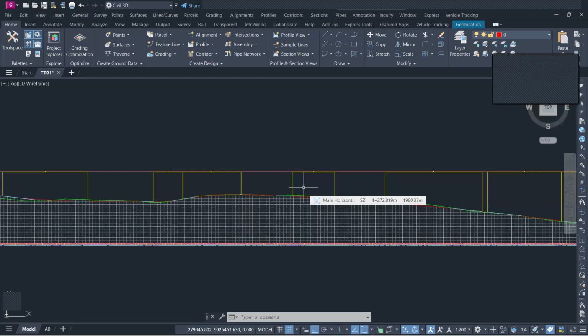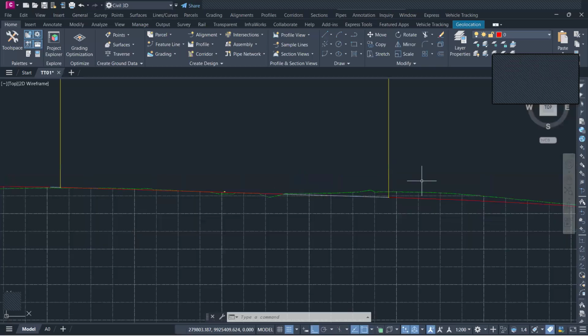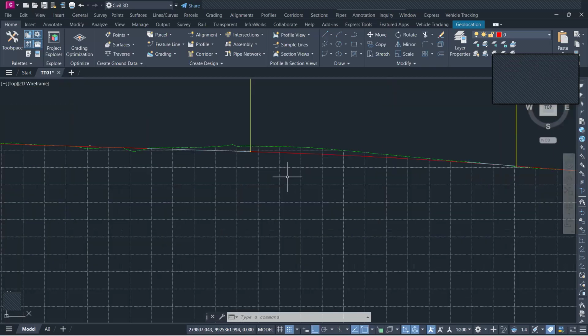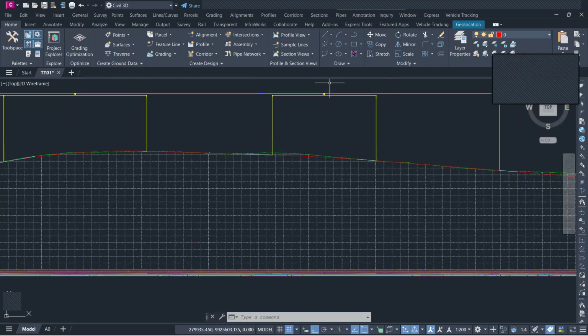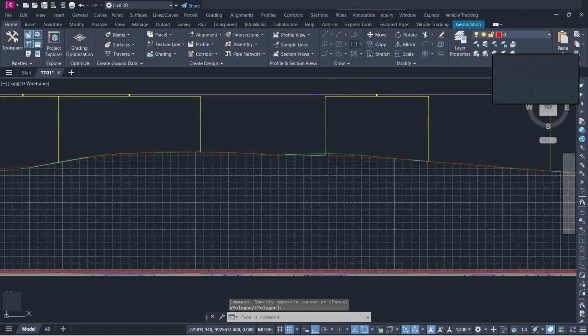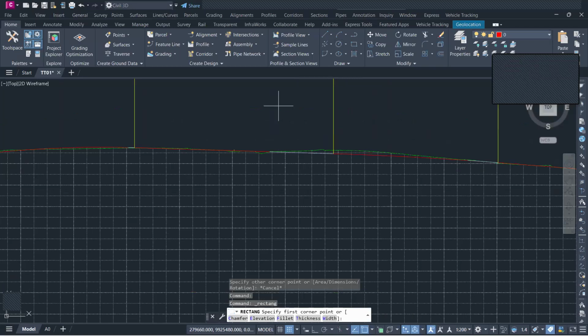But if this material is of good quality, let's say you find that it's gravel, it's possibly some good material, maybe some red soil that does not have a lot of problem with swelling. So if you find that the swelling is within the limit, then you can use that material as a subgrade. So as you design your profile, this is the other thing. Well, you already designed what you have here. But then you need to look at the alignment report from the materials engineer, and he is going to tell you possibly, let me just draw something.